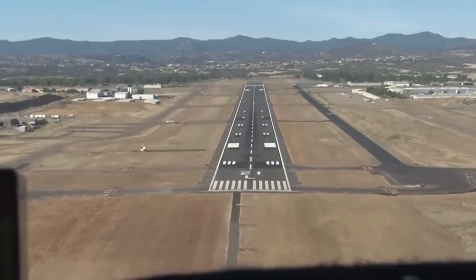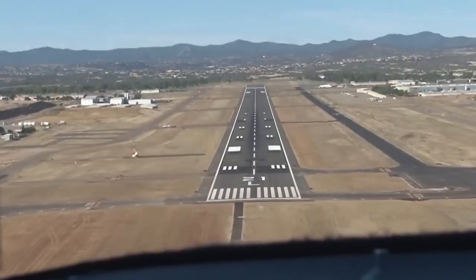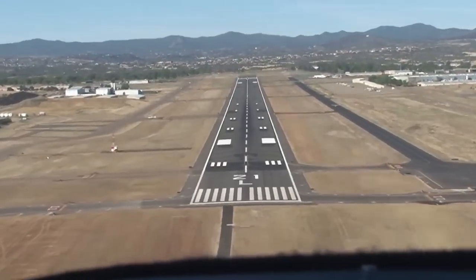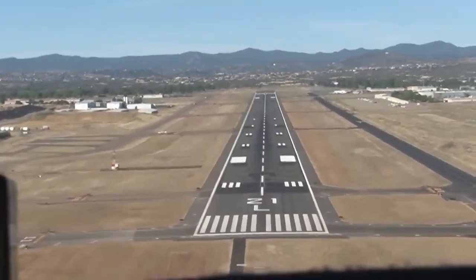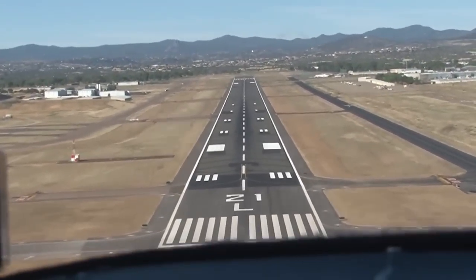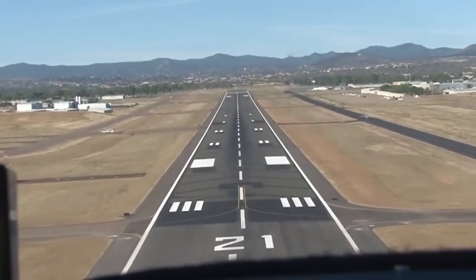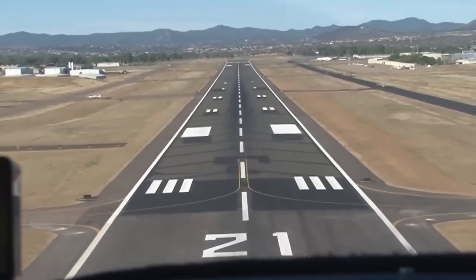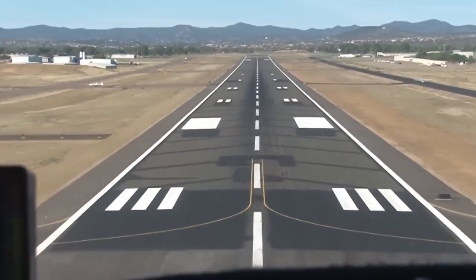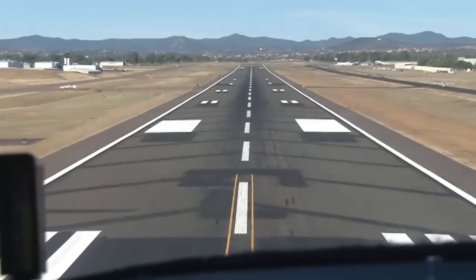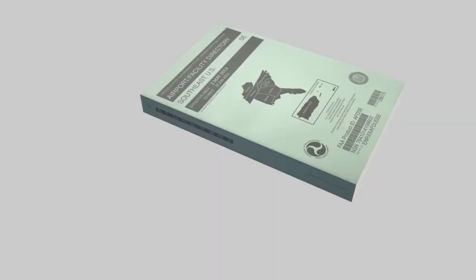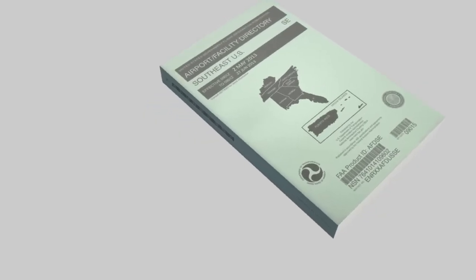As airports become encroached by homes and developments, the pilots and airport operators may have to deal with noise complaints. At some airports, the pattern procedures may be amended to minimize the overflight of the more noise-sensitive areas. Nighttime curfews or restrictions to training activities such as touch-and-go landings during certain hours may also be in effect. To find if noise abatement procedures exist in an airport, you can consult the AFD or similar publications.